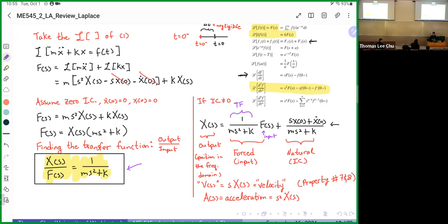So if I were to have a generalized equation where I don't know if initial conditions exist or not, the right side's the full solution. So the right side is actually more correct in that sense because it applies to both 0 and non-zero initial conditions, because we can always just make them 0. Then when we make them 0, it becomes the transfer function, because the transfer function only looks at the input response, which is the first term. So right here, this is just the forced response.